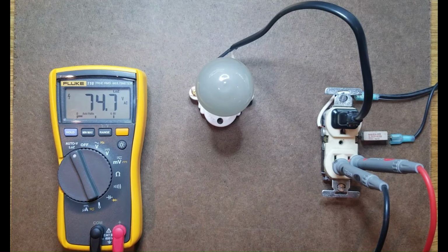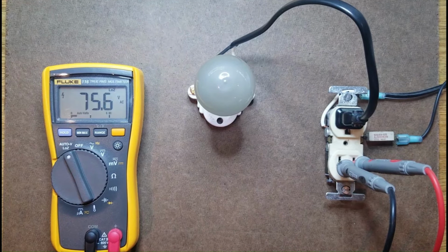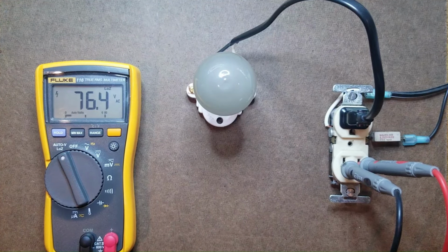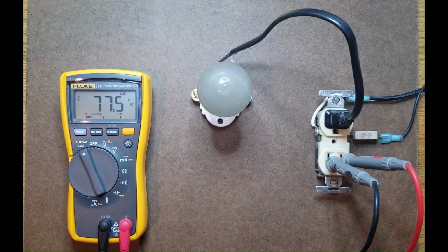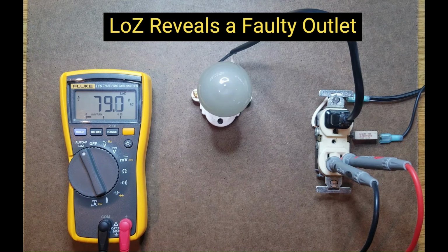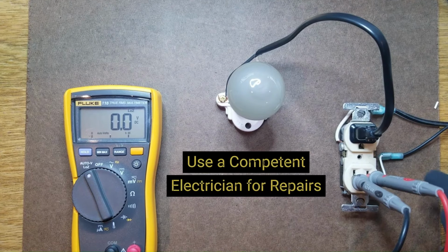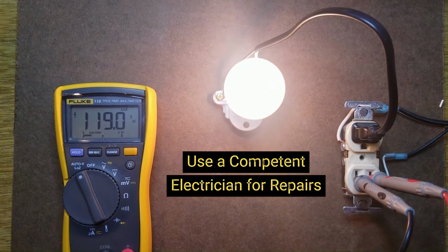So by using a LoZ meter with this outlet that has an upstream loose connection of a couple thousand ohms, we're reading 75 volts because this was putting a load on the circuit. And the voltage is being split, the 120 volts being split between this resistance here and the internal resistance of this meter. So this tells us we have a bad outlet. So the solution here would be to repair the loose connection, so that you have a solid voltage source again, and then you'll be back in business.